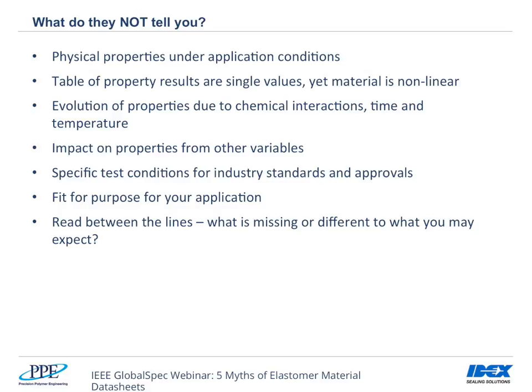Any industry standards or approvals that the material has been subjected to, if anybody's ever read any of these standards, you will notice that there are variables that can be selected, and therefore one material that's been tested to standard versus another material, they could actually have two completely different tests yet have the same approval. Ultimately, it doesn't tell you whether the material is fit for your application or product.